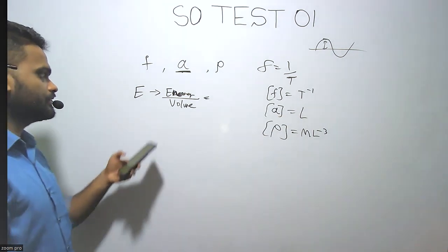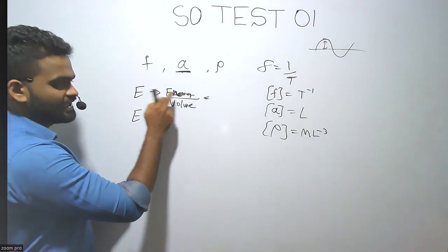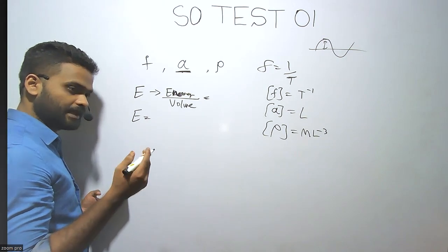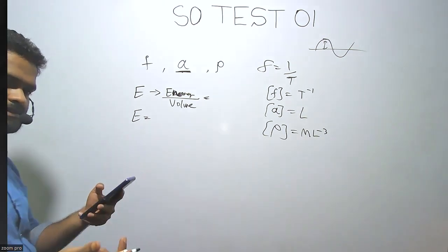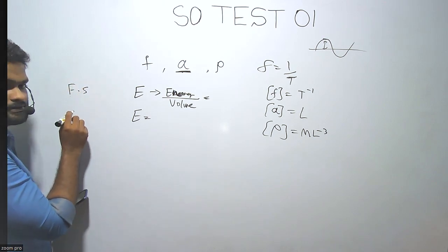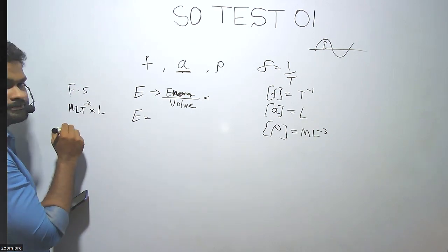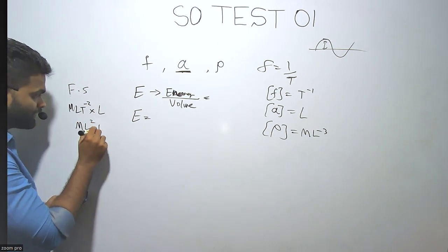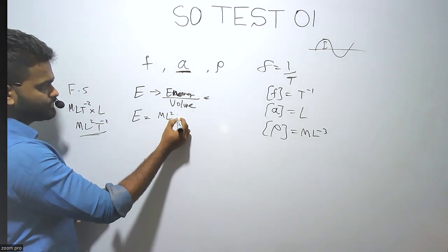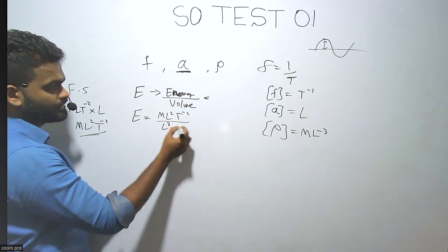Here let's derive the dimensions of E. Energy and work have the same dimensions, they are similar things, right? So energy also has F times s. Dimensions of F is M L T minus 2, s is L. So you get M L squared T minus 2. Then you need to divide that by volume, L cubed.